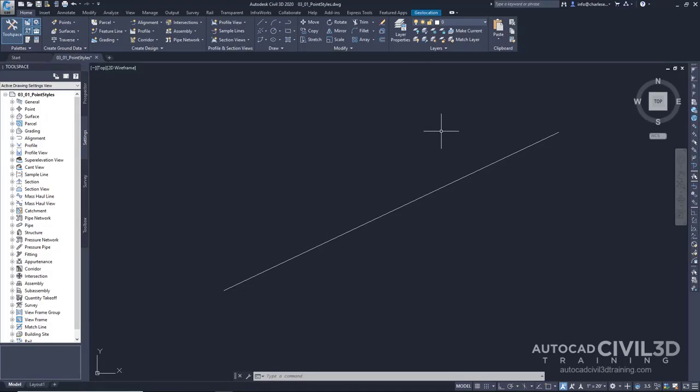Points that identify a linear shape can include curb lines, corners of buildings, or a center line of a road. Having an X marks the spot point isn't as critical for a linear shape as it is for identifying objects. Points that identify objects include marking the location of trees, manholes, utility poles, and different structures. These points symbolize the object you're marking, so it really should resemble the structure the point is identifying.